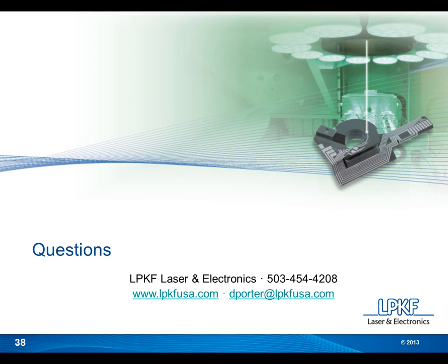All right, thanks everyone for taking part in that poll, and we're going to go ahead and dive into the questions now. So the first question I wanted to bring up is one I think we'll bring in Don for. Eric wanted to ask, can the interconnection be formed between the top side and the bottom side, basically equivalent to vias in a PCB? Is the laser able to activate these holes? If yes, is the plated hole left in the final product, or do you have any way to cover or fill the hole? Don. Okay, so starting from the beginning, there are two ways to do front-to-back interconnect with an LDS process.